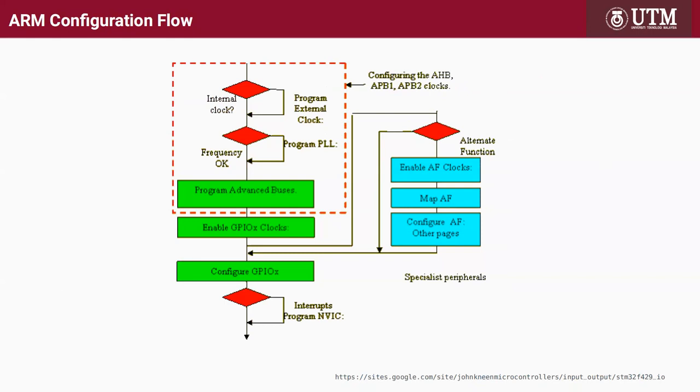There's clocks there that you have to know. Okay, so you have to know which one you want to use. Is it a local clock, internal clock, external clock? Are you going to reprogram the PLL? Okay, and then you have to know the frequency. Okay, and then you have to enable the clock to the GPIO. Okay, if you don't enable the clock to GPIO, you cannot use the GPIO.